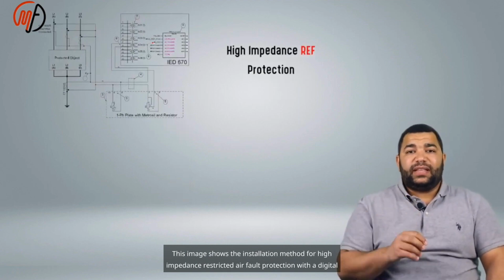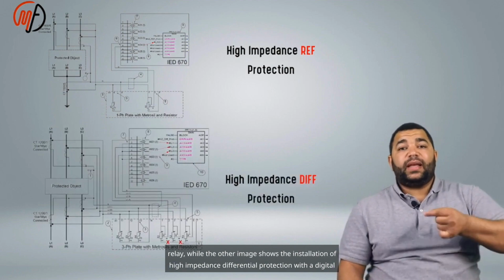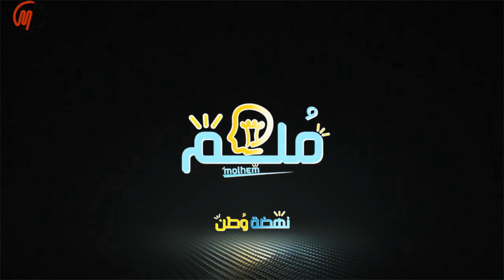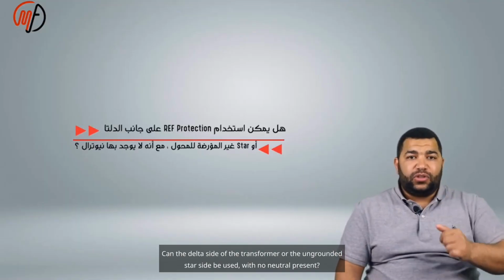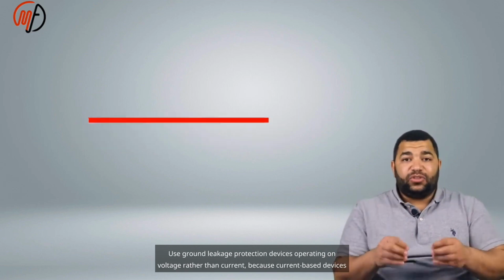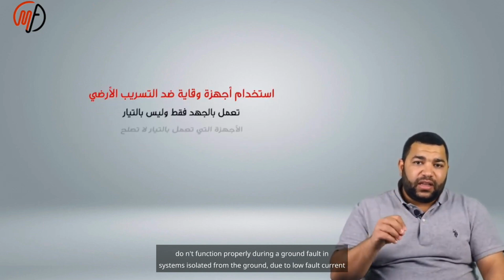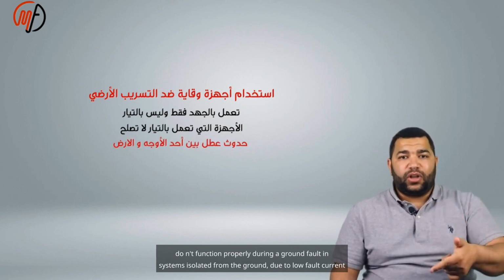This image shows the installation method for high impedance restricted earth fault protection with a digital relay, while the other image shows the installation of high impedance differential protection with a digital relay. Can the delta side of the transformer or the ungrounded star side be used, with no neutral present? Use ground leakage protection devices operating on voltage rather than current, because current-based devices don't function properly during a ground fault in systems isolated from ground, due to low fault current.